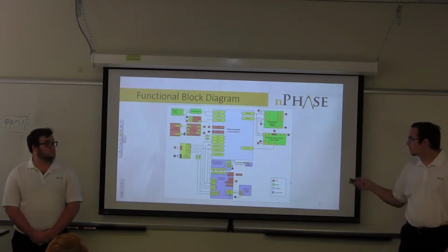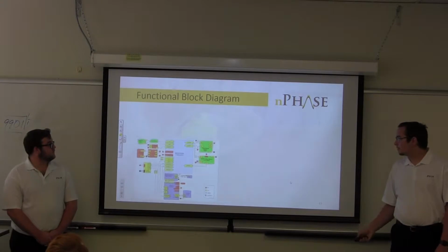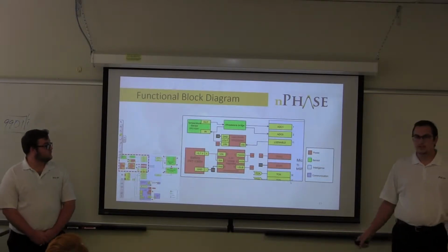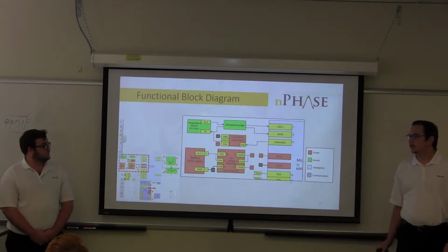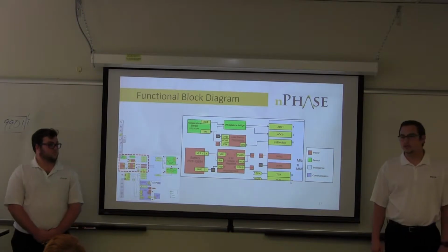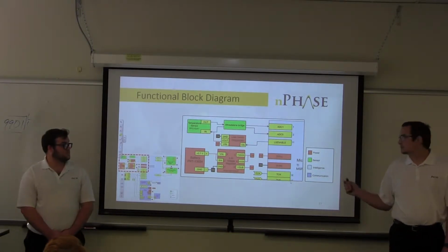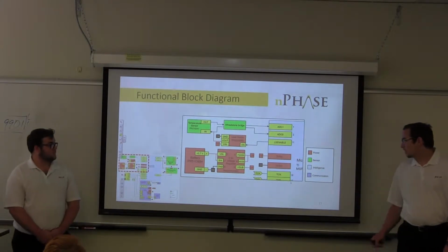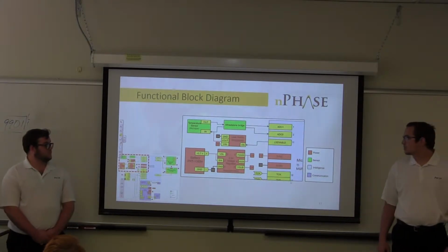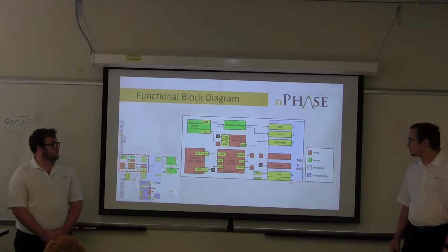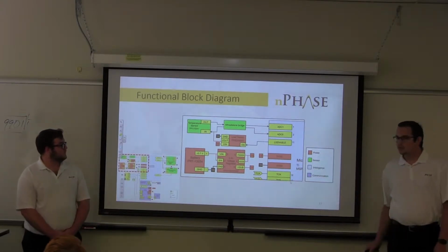We're going to zoom in so you get a little bit more detail and be able to read a little better. This first section includes our battery and our voltage regulator. It is a 3.7 volt battery, which is going to be using the voltage regulator to go down to 3.3 volts, as well as another output of 3.0 volts, which will be used to power our load switch.